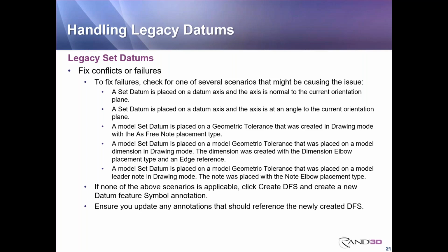So what you can do is go to the navigation area in your environment, in either the drawing tree or the model tree, select the draft geometric tolerance, and then hold down your right mouse button. You're going to get the edit references option, which actually appears in the mini toolbar, so you can get that from left click too. From there, you can select any appropriate references on the model, and then you can proceed from there.